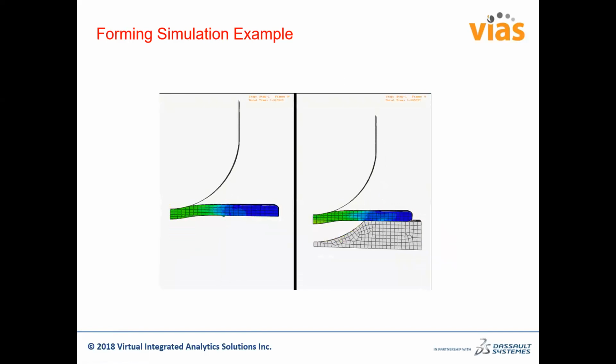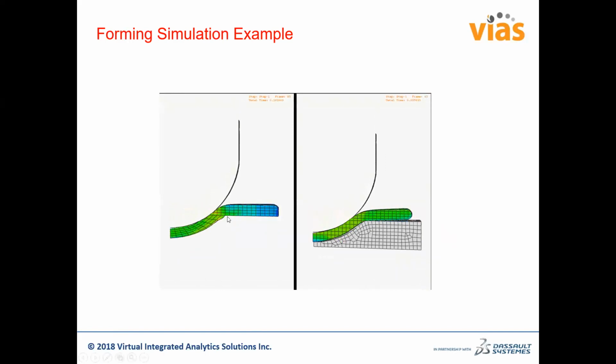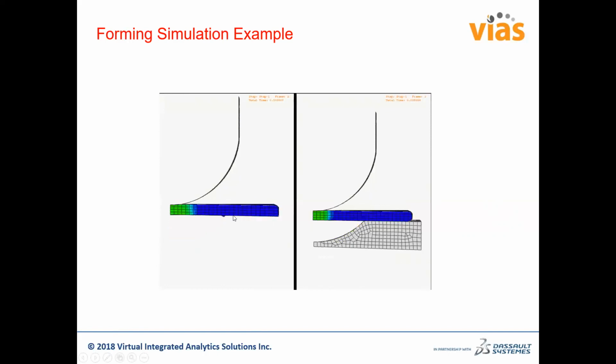So yes, the only way to specify the constraint at this contact was to define a contact with a rigid body. But now you can actually constrain the motion of the material on the CEL boundary to not move in a certain direction. It will actually stop the flow along that direction.